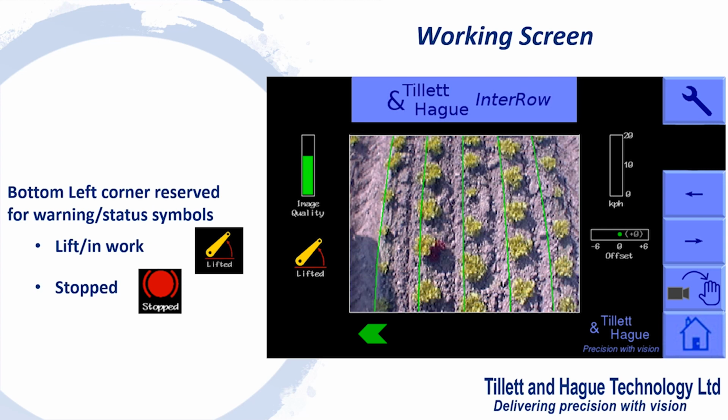A warning triangle indicating poor tracking is displayed if estimated lateral error exceeds 25 mm. On seeing this warning, users should check performance on the ground. If enabled, the warning triangle will be accompanied by an audible warning.